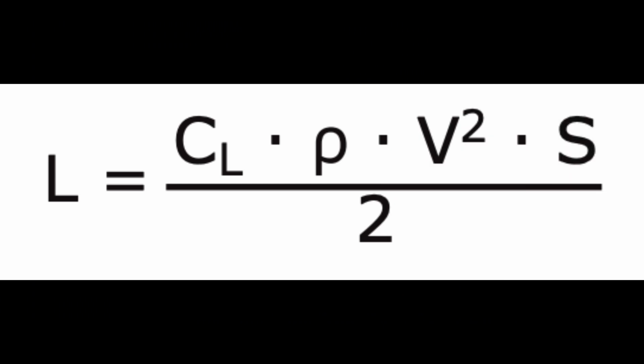This is accomplished by the forward speed of the aircraft. Lift is proportional to the square of the aircraft's velocity. For example, an airplane traveling at 200 knots has 4 times the lift as the same airplane traveling at 100 knots, if the AOA and other factors remain constant. The above lift equation exemplifies this mathematically and supports that doubling of the airspeed will result in 4 times the lift. As a result, one can see that velocity is an important component to the production of lift, which itself can be affected through varying AOA.